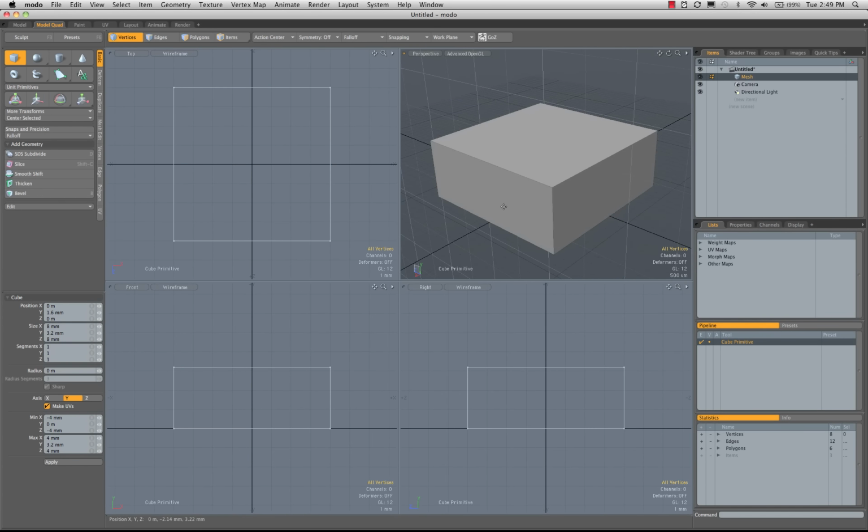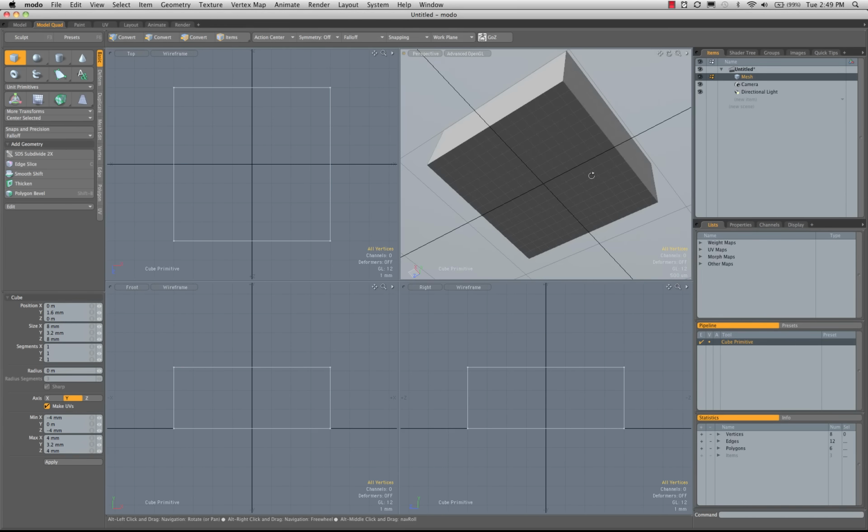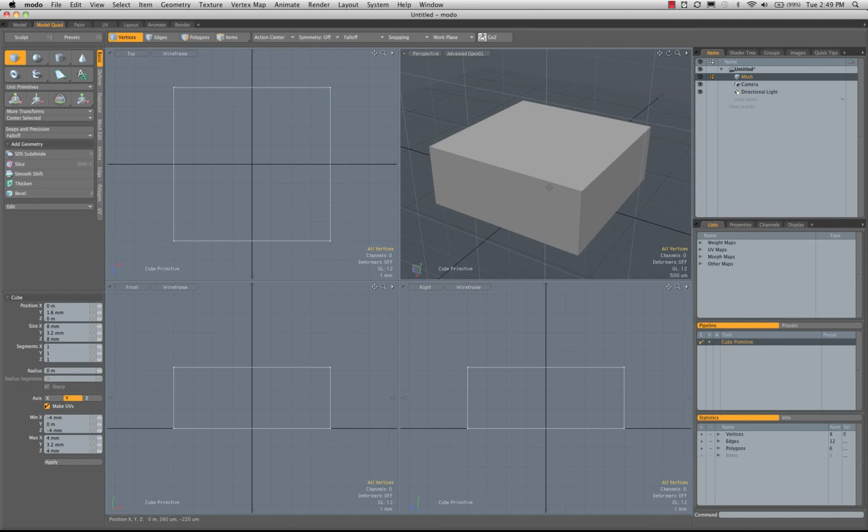Now, one thing about these little toys is that there is this level of inner symmetry, kind of divisions of a 0.8 millimeter scale that kind of crop up everywhere, and we'll see those as we go on constructing here. We're going to be doing this with subdivision surfaces, so I guess the first thing you might ask is why subdivision surfaces instead of just making this polygonal, since it is pretty much polygonal. It's a cylinder with a square-shaped hole in the bottom. So why are we going to do it this way?